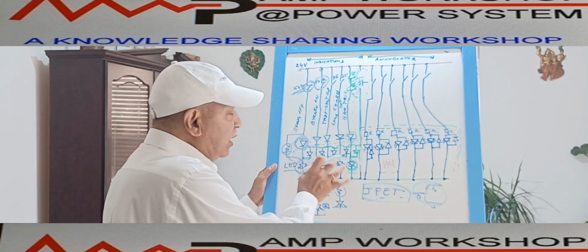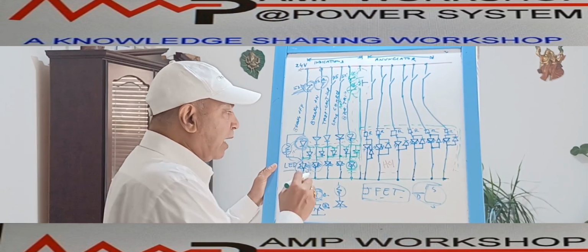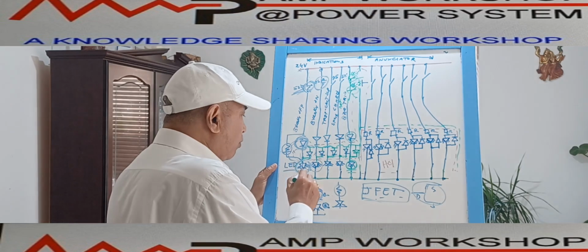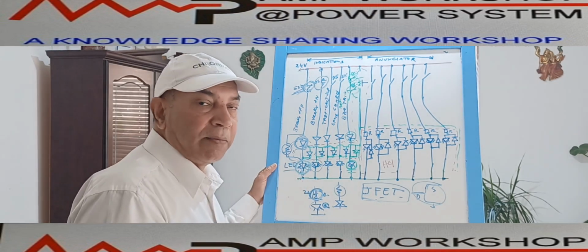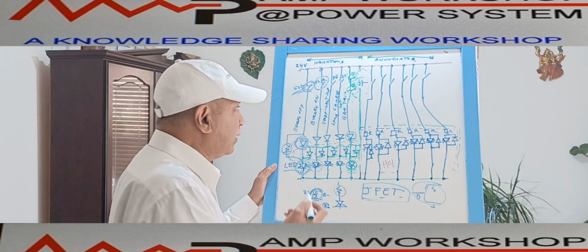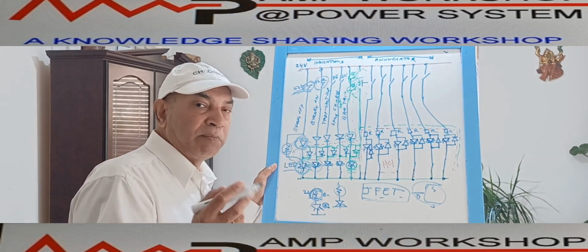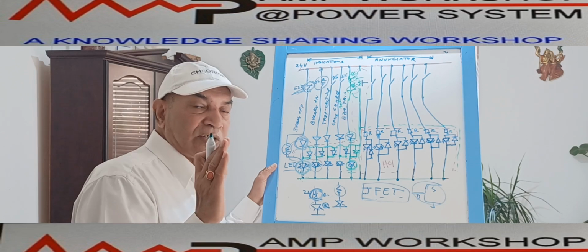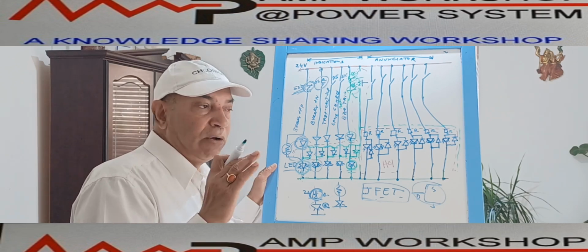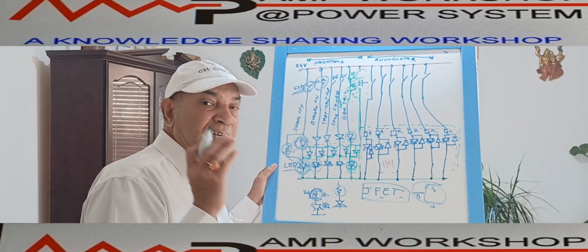So these are the three indication lamps. Normally I have said that the healthy condition is monitored by the green lamp. But sometimes customers want, when the breaker is on, meaning the circuit is energized, to make that clear, because if anybody does something on it, it will cause danger.